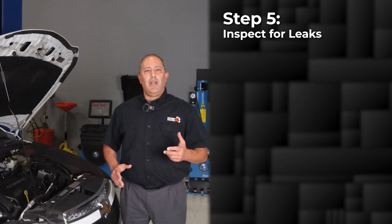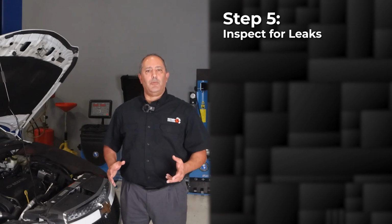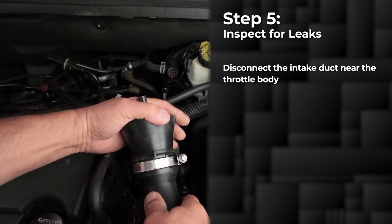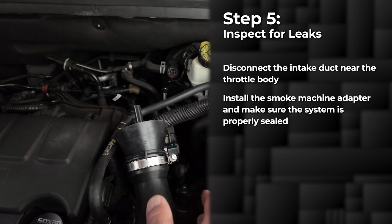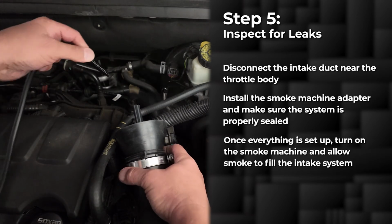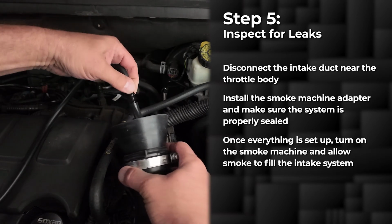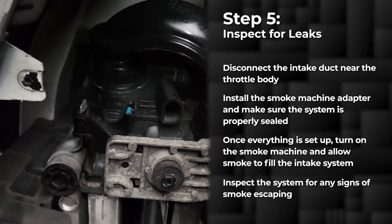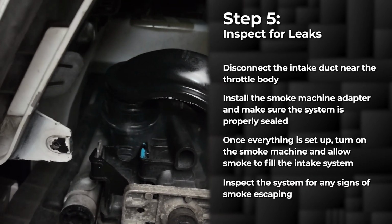To check for possible vacuum leaks, we'll use a smoke machine. First, disconnect the intake duct near the throttle body. Next, install the smoke machine adapter and make sure the system is properly sealed. Once everything is set up, turn on the smoke machine and allow smoke to fill the intake system. Then, inspect the system for any signs of smoke escaping.